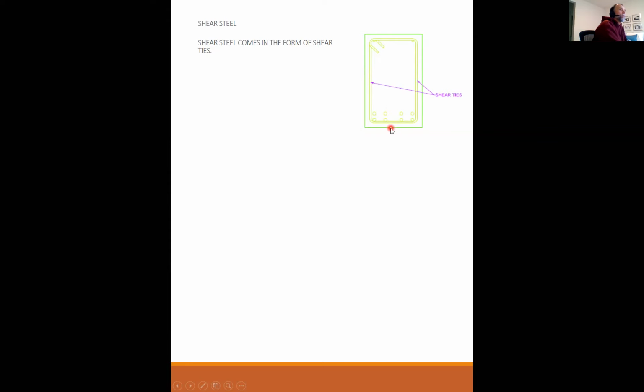And you need to know how big the shear tie is so that you can make an approximate how deep is d. Where's the center of that steel is kind of based on how big that shear tie is. But now we're actually going to be using these ties for design. So these pieces of steel are actually a design item.